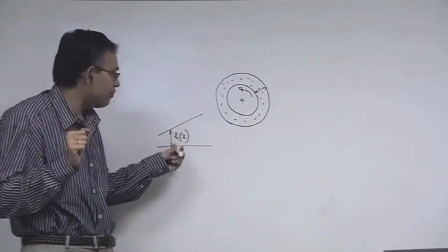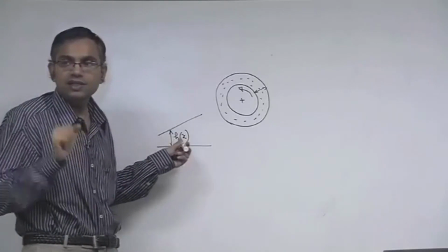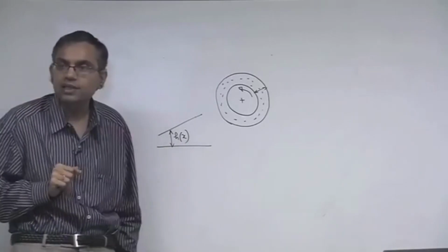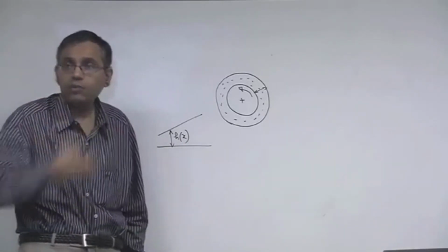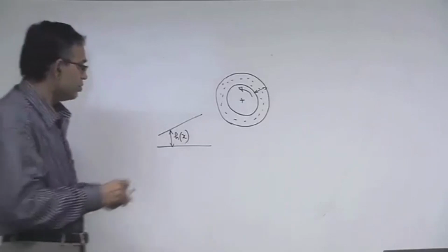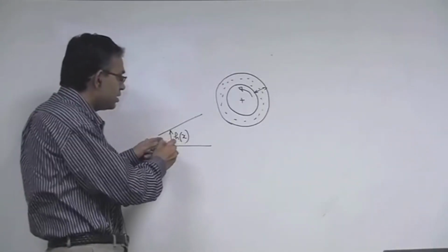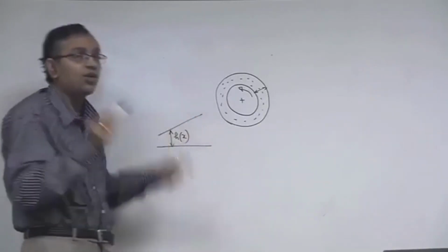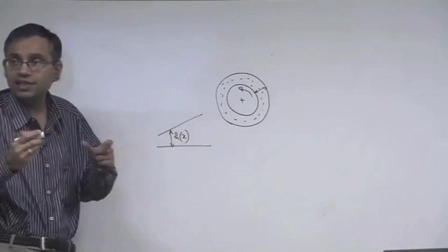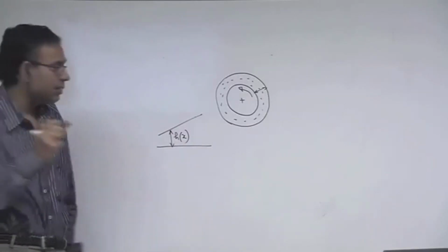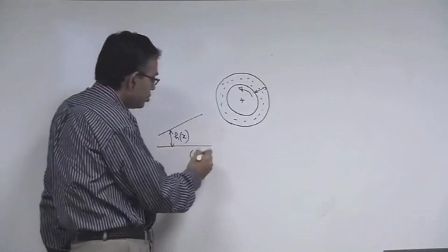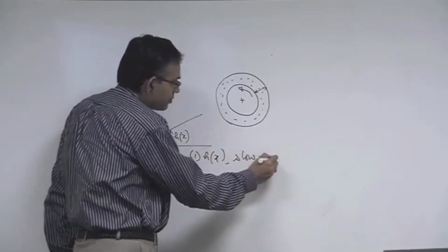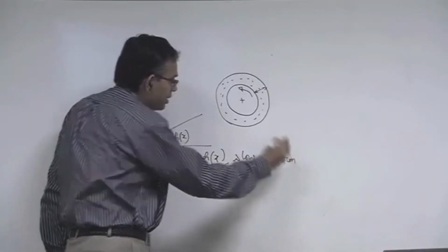Not only that, the flow passage has a constant cross section; the cross section is not changing. Now, what about the situation when the flow passage is a function of x, but it changes with x slowly, not rapidly? This is number 1. So, h is a function of x, although it is a slow variation, not a rapid variation.